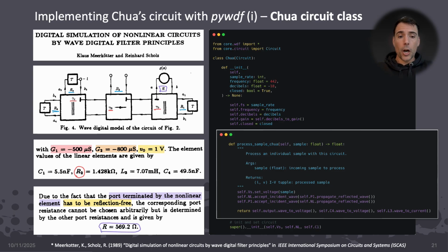In order to extract our signals of interest, the X, Y, and Z of our chaotic system, corresponding to the voltages across the capacitors and the current through the inductor, we need to adapt an asynchronous handler that WDF provides us to probe specific elements that have been stored in the tree structure. This required extending the WDF library with getters that not only convert from wave digital to voltage, but also to current. A small detail. So now we can return a tuple of the signals of interest.